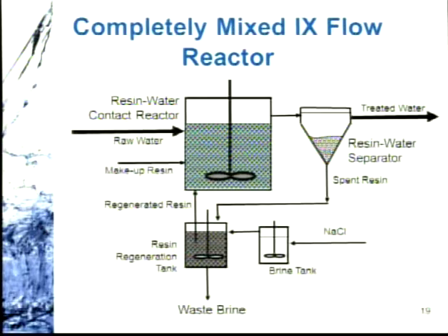So all that salt that you push through a primary treatment pressure vessel for a standard packed bed column is not put directly into the process flow. It's done outside in a resin regeneration tank. And that gives some flexibility for the regeneration process that packed bed systems don't have. So I think you'll hear a little bit more about that. It has advantages, and it's just a different way of going about it.